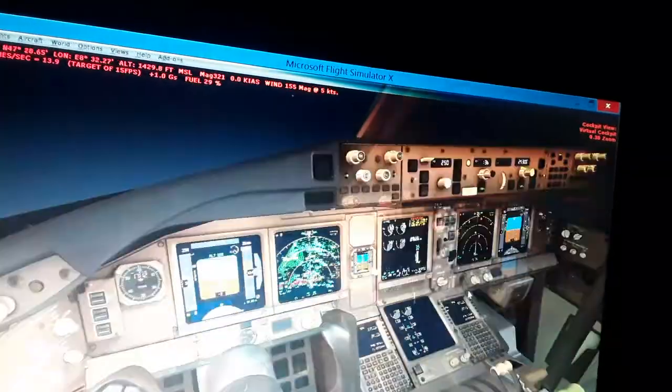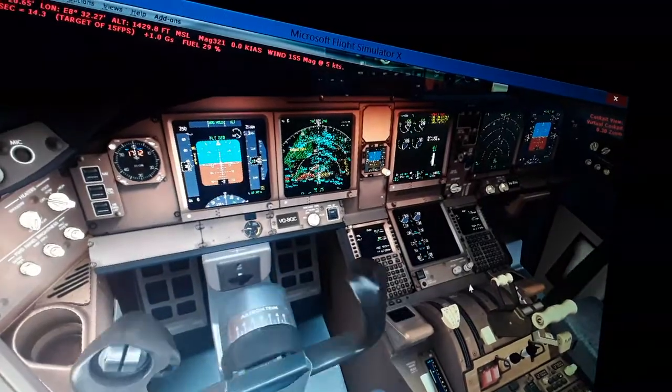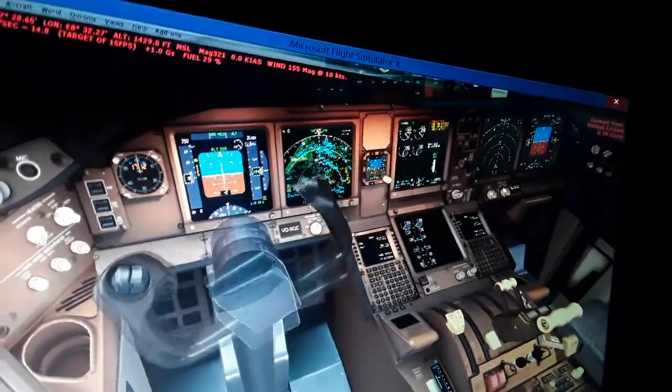So you have to know something about flying the aircraft. So I come again into the cockpit. You can see here we have the control yoke, the control column, and the control wheel, which pitch the elevator up and down. So you can see I'm using this side stick here for flying this aircraft, which is an Airbus side stick, but you can use it for the Boeing. So you can pitch up and pitch down the elevator, also bank and roll the ailerons, and also use the rudder pedals for turning the aircraft left and right, and the nose wheel steering on the ground.